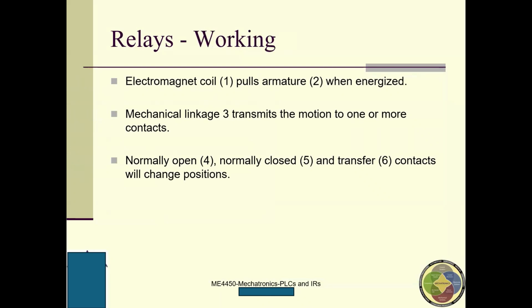The electromagnetic coil 1 and pulls armature 2 when energized. The mechanical linkage 3 transmits the motion to one or more contacts. Normally open, normally closed, and the transfer contacts will change positions.